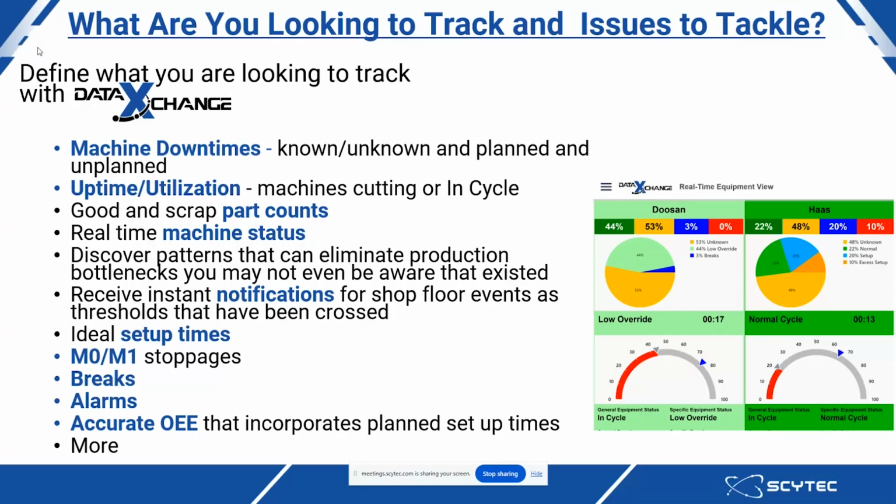You can receive instant notification for shop floor events as thresholds that you define have been crossed. You can also track ideal setup times, M0 and M1 stoppages, breaks, alarms, and also accurate OEE information that includes planned setup times as well as a host of other things.